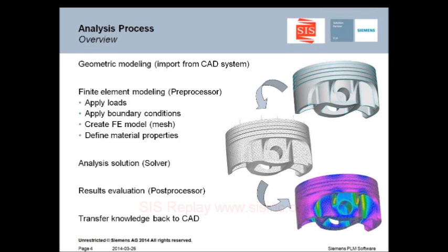The model is then submitted to a solver for analysis, and Femap is bundled with the solver NX Nastran, which is a pretty good solver for stress dynamics, and has some advanced nonlinear capabilities as well. Once the analysis is finished, we bring the results back in, or actually I'll show you another way of accessing results a bit later in the presentation, where we can then actually view the results and see how the design has behaved according to the loads and boundary conditions that have been applied.